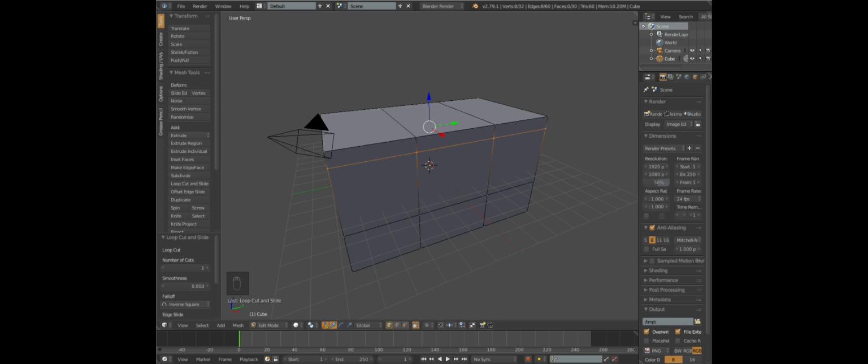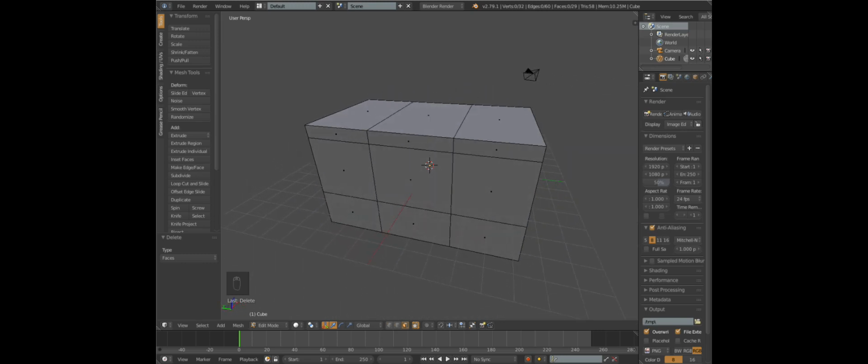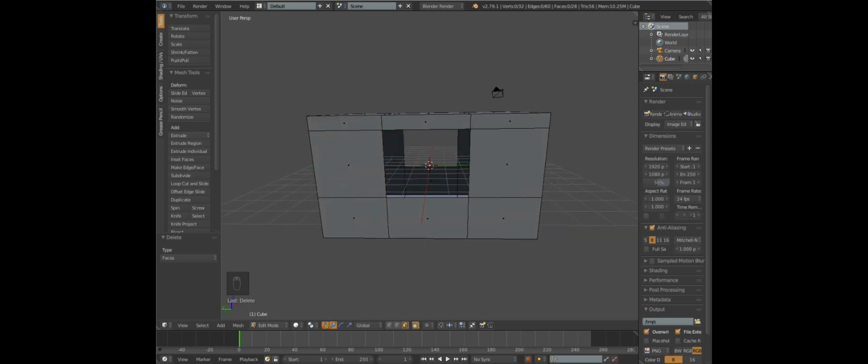Alright, so we're in edit mode, and we're selecting the vertices right now, and we're going to click on face down in the bottom here, and we'll click on one of these faces, hit X, and then delete faces. I think if you do only faces, it's the same thing in this case. That opens up into our cube, and then hopefully everyone has figured out how to move the view around, but we'll flip over here. I just middle mouse buttoned and then rotated, click this one, hit X, and then again hit faces. So if we look down here, we've got two windows kind of opened up.